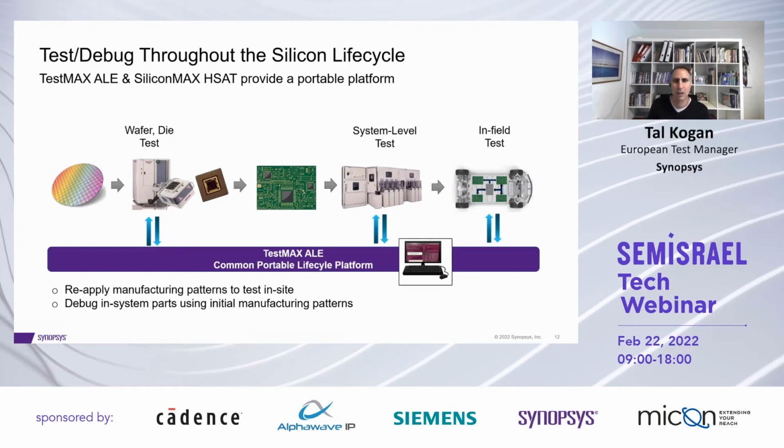So again, the combination, how would it look like? Remember, the purpose here is to test the dies. So you need the testers to support that, and I'll show that later. But I can utilize this combination in order to test your parts, whether those are packaged dies that you test in production, or whether those are already in-the-field dies that you want to do in-field tests on.